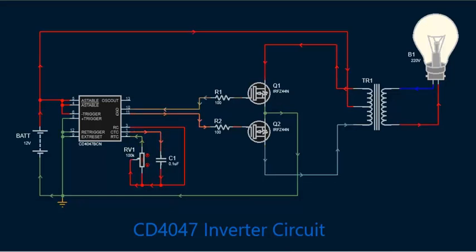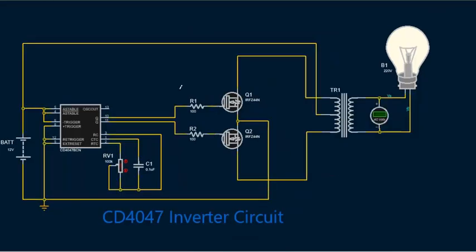First, I will show the high voltage spikes produced by the transformer switching at the MOSFET's drain. For this, I will place a voltage probe at the MOSFET drain. I will now plot the graph of the signal at the drain.